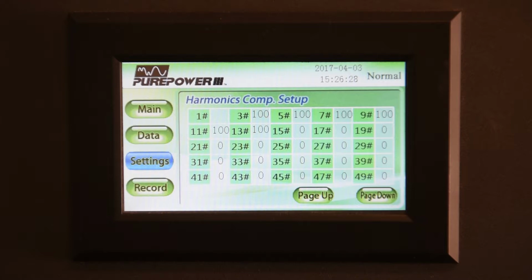In a 6-pulse system, a standard system, you're generally going to want to correct for the 5th and 7th harmonics. Those are most important. The next harmonics will be the 11th and 13th, and then your 17th and 19th. And if you correct for those harmonics, generally that is sufficient to provide pretty clean power to the system.